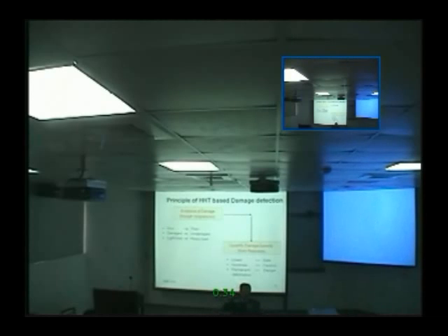If under heavy load the relationships start to bend, in other words, they get beyond the linear stage into the nonlinear range, then we start to have problems. So light load versus heavy load is a very important indicator for the health of the bridge. With that, we can define the existence of the damage and quantify the severity. Even more important is using the linear-nonlinear criteria.